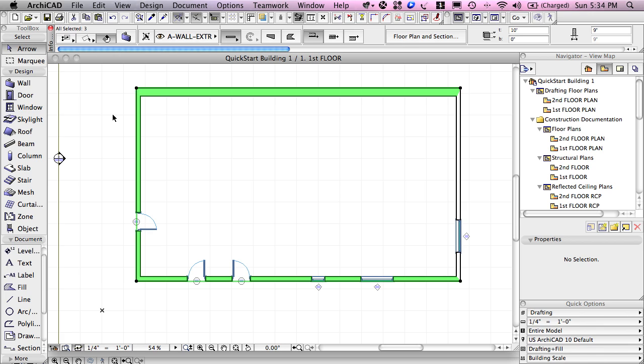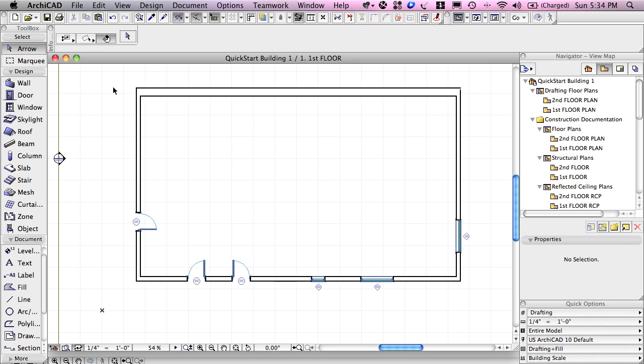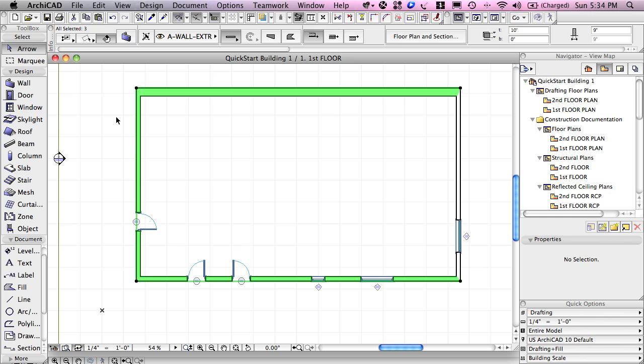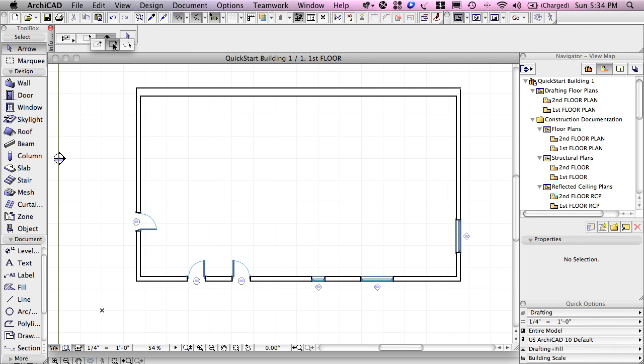So I'll click an empty space to deselect, and now when I want to select here, if I click 2 points, this determines a rectangle, and then I can select things there. In this case, it doesn't make much sense, but sometimes a building has parts of the design on an angle, and this can make it easier to select those elements on a similar angle here. So let's put it back to the most standard one, which is a rectangle, and my preferred one, which is the partial selection. That works most of the time, I think, the simplest for our use.